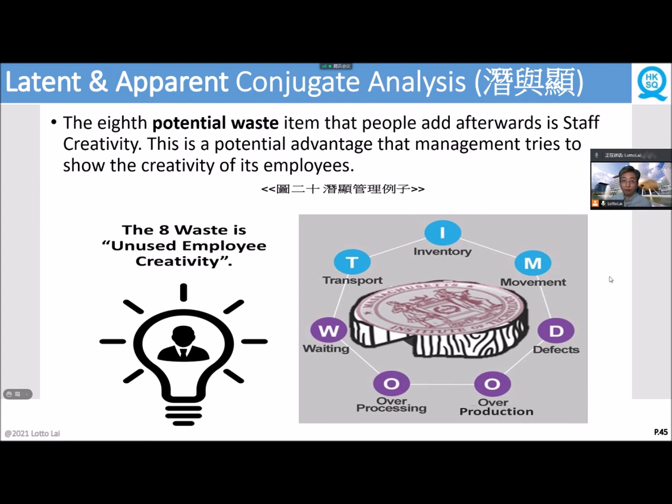It is one example. When we are teaching quality management, we use lean manufacturing. In the lean principle, we have the 7 wastes. I'm using this MIT word so it's easier to remember: excess motion, excess inventory, transportation, waiting time, overproduction, over processing, and defect.